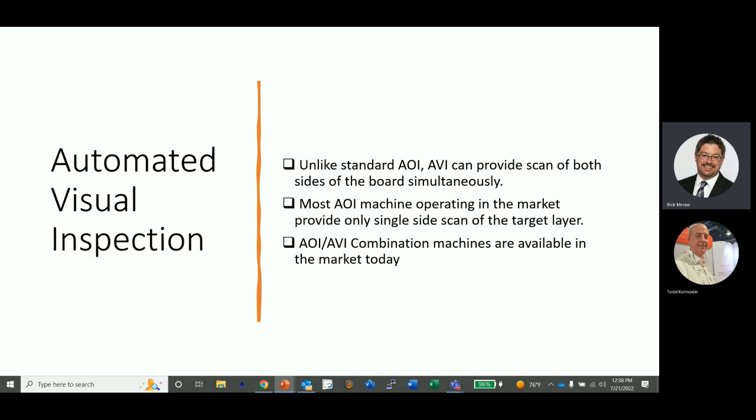Sometimes very consistently, and then there are others where, maybe getting towards the end of the shift, you may miss something. There are all different tricks of the trade to try and catch these defects, but what's consistent is the AVI will always catch these defects, and maybe it catches some defects that are not necessarily deemed bad. They're deemed acceptable by the IPC standards.